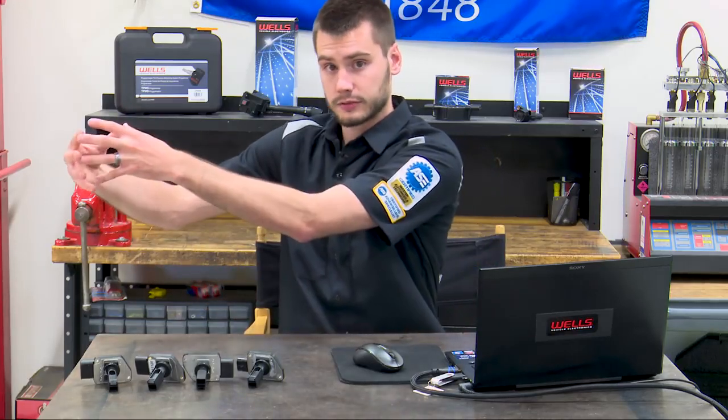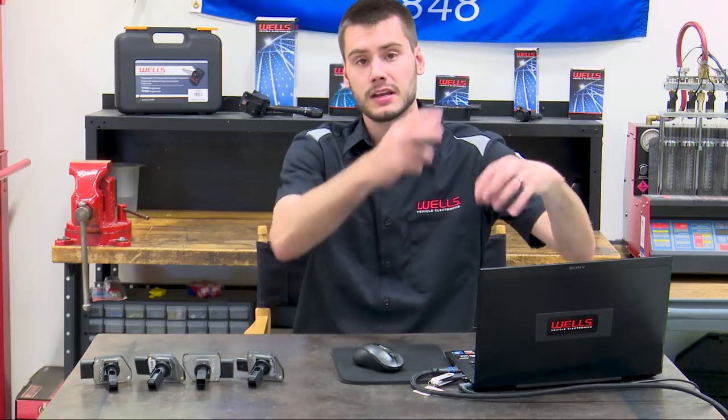Technician B is also correct, because if that purge solenoid is sitting there in the intake manifold, drawing all those vapors out, what happens when that canister doesn't have any vapors in it? Well, our vent solenoid, which is after the canister, is open to fresh air all the time. So if we put vacuum on this side, we draw all that fresh air in through the system into our intake manifold, causing an excessive amount of oxygen past our oxygen sensors, creating a lean condition. So the answer to the question is both technicians.